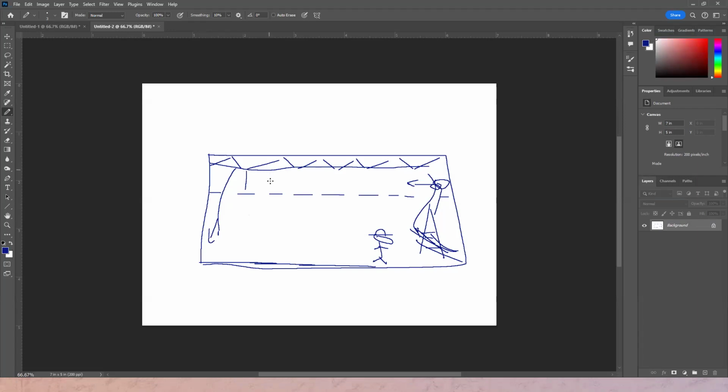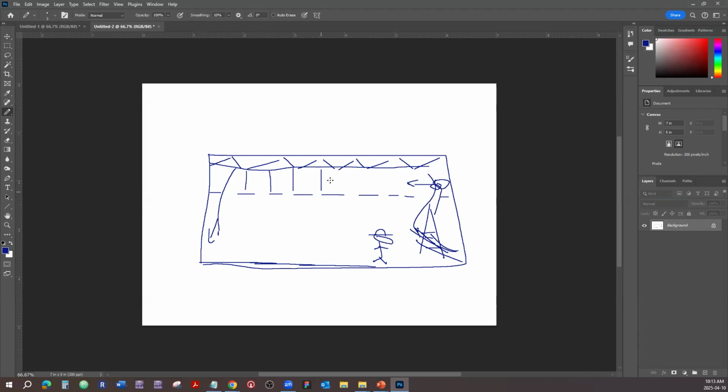they're sitting on the frame, like an aluminum frame, and that frame is supported from the true ceiling. Quite often the supports are driven into the concrete there. They're suspended by those iron rods. Many years ago, what people would do is just have the wires run right on top of the ceiling tiles, and then bring them up and tie them to the rods that are holding the ceiling tiles frame.